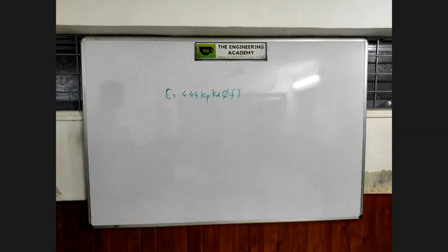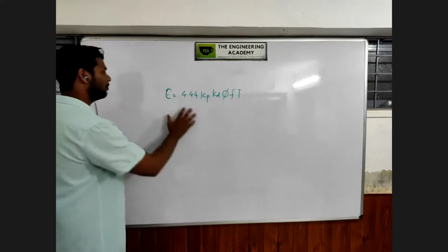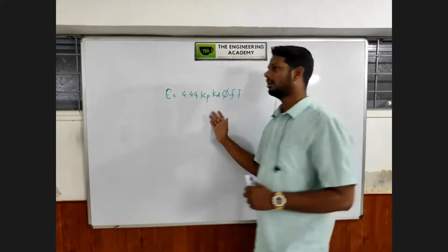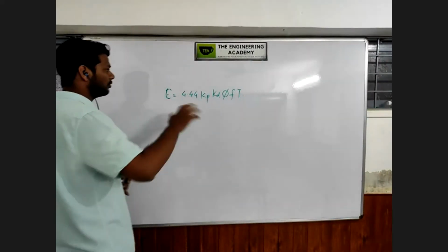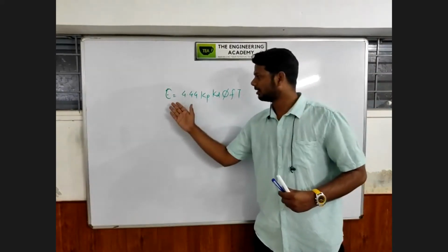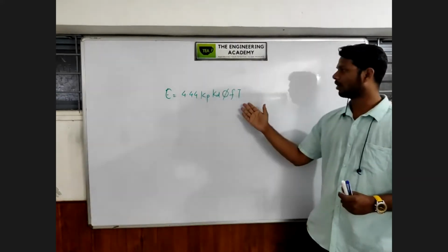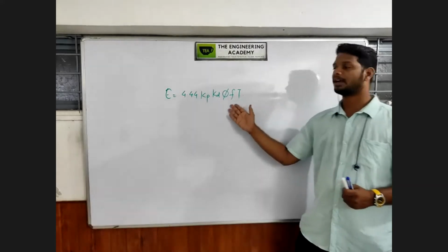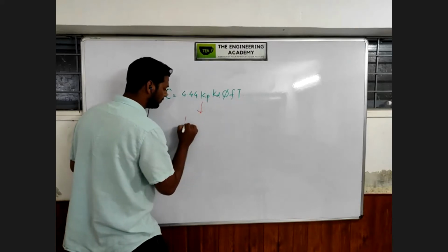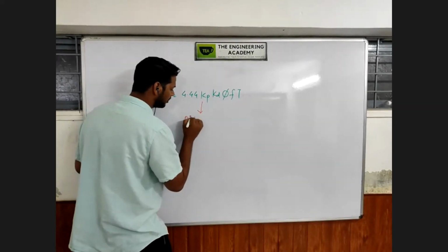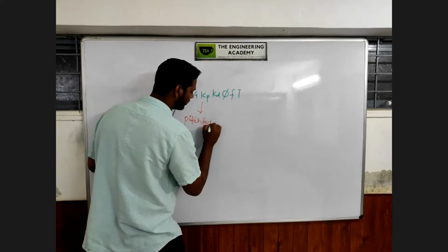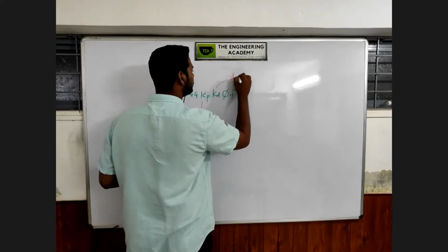This is the most important formula, and maximum questions were asked on it, not exactly on the formula, but conceptual questions related to it, such as: in a synchronous machine, induced EMF is directly proportional to what? It is directly proportional to Kp, Kd, flux phi, F, and T. So what are these quantities? Kp is called the pitch factor. Kd is called the distribution factor.